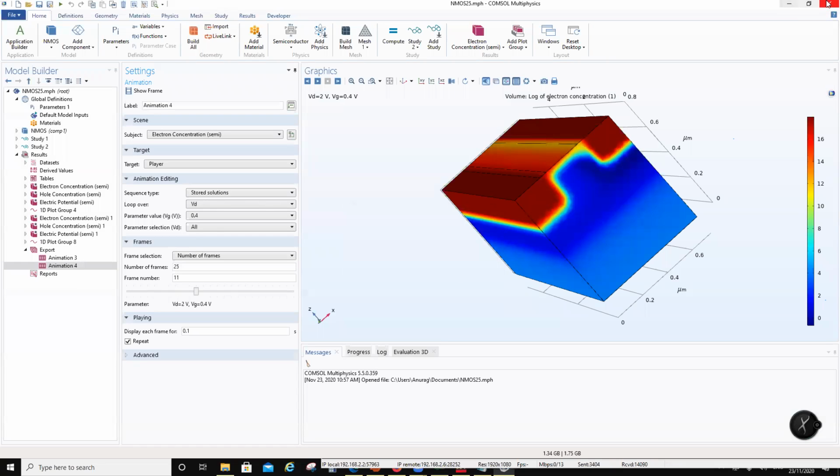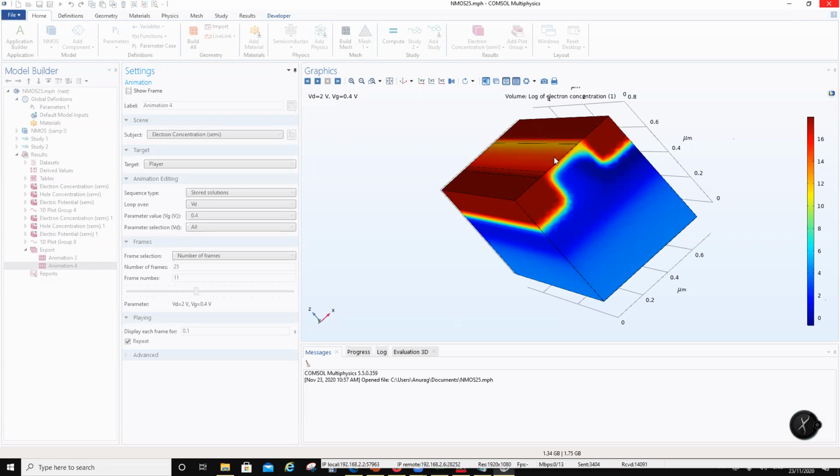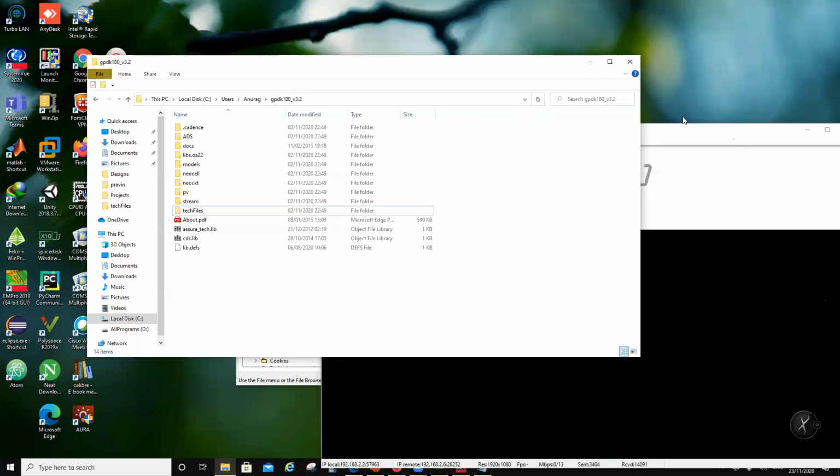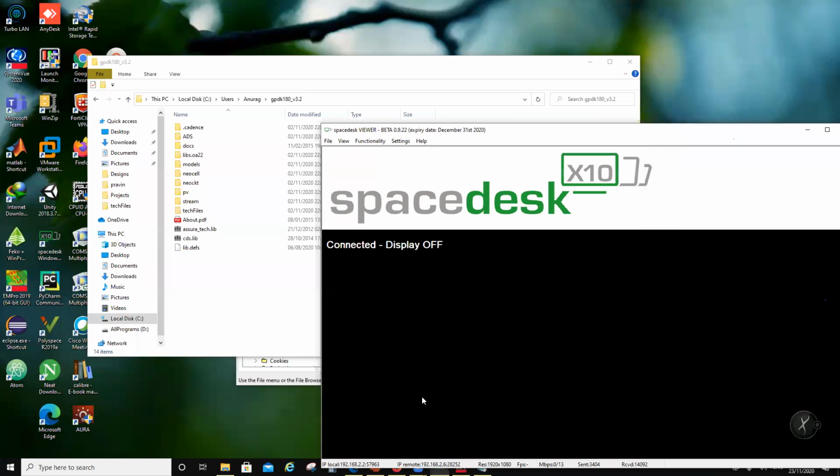But this is not possible in EM simulation, which is a Laplacian solver. Circuit simulation is a Runge-Kutta method-based solver. It solves ODEs, right? While Helmholtz equations are solved in a Laplacian solver based on techniques like method of moments, FDTD, and all that, right? So different simulators are for different applications. EM simulators are for EM simulation where there are no electrons and holes, right? Okay, so I guess I answered your question.